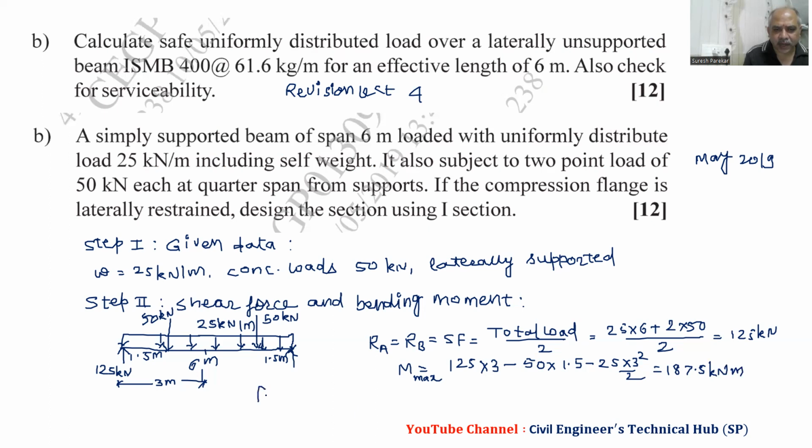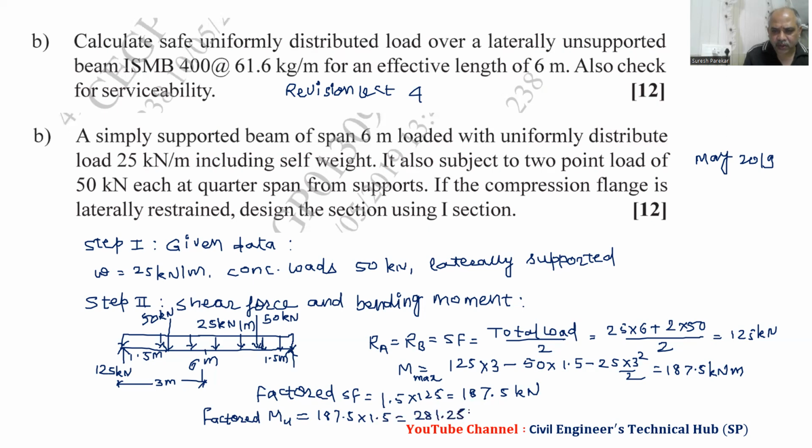We have factored values. Factored shear force is 1.5 into 125, and it comes 187.5 kilonewtons, and the factored moment, ultimate. So factored M max or Mu is 187.5 into 1.5, 281.25 kilonewton meter. So this is the main part. Then the remaining part is the same.